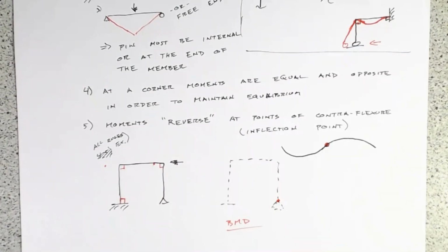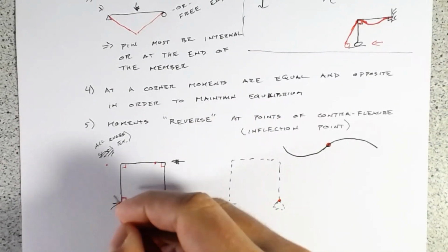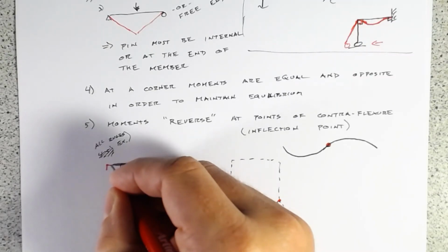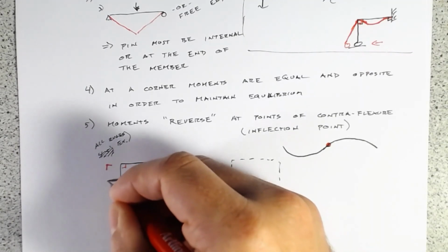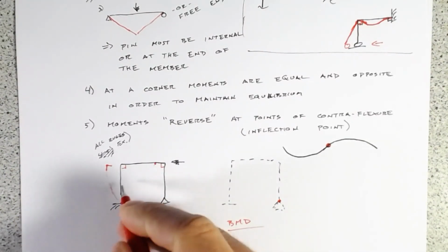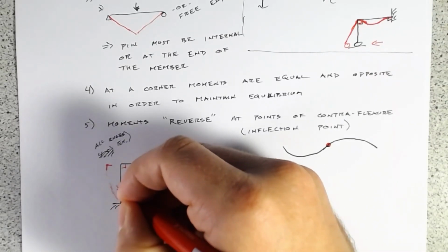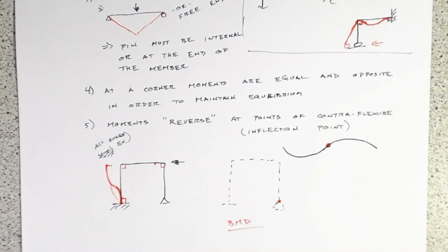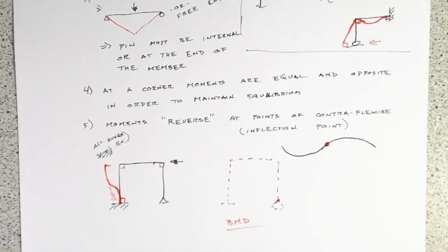So if I'm going to start on this column and displace it over here, I know the base has to stay put, and I'm going to have some 90 degree. Is it going to bend like that? Well, it can't, because my base is grabbing it. I can't rotate the base, so it's got to come straight out of the ground. And it's going to kind of do this S-shape thing here. And you can grab a little stick and you can see that.